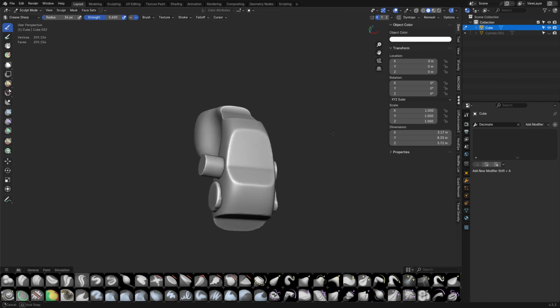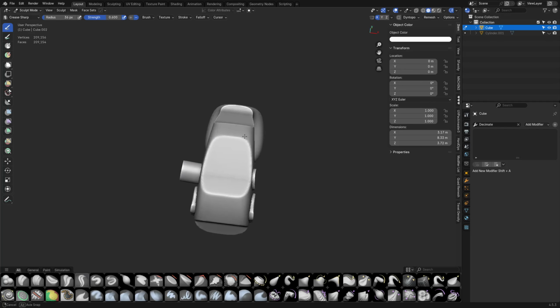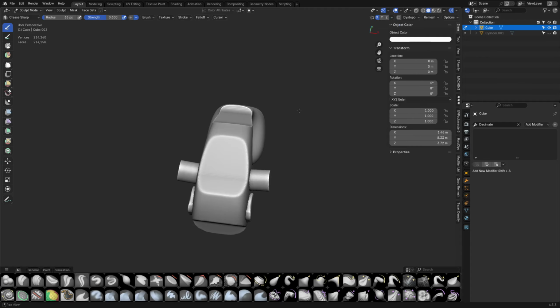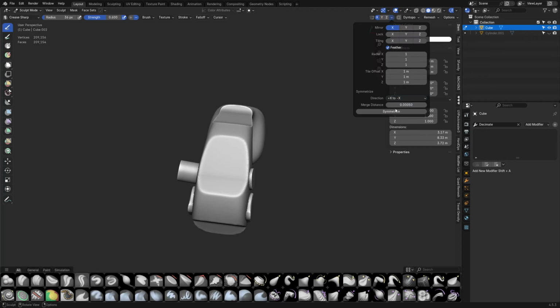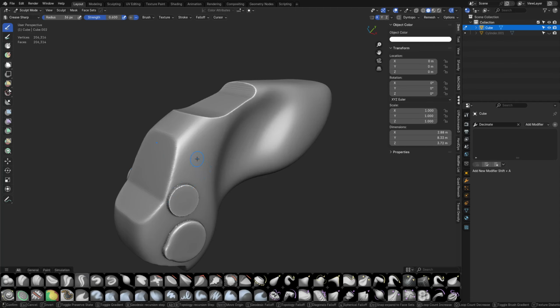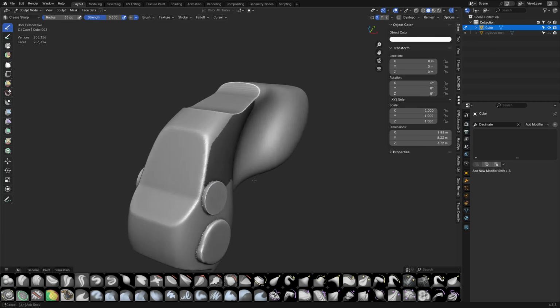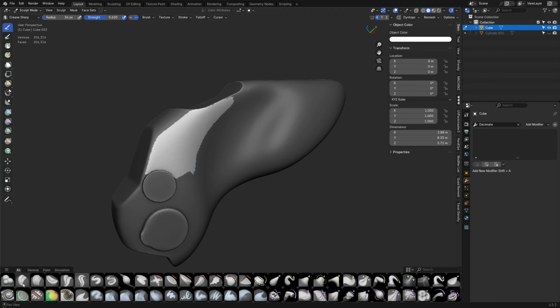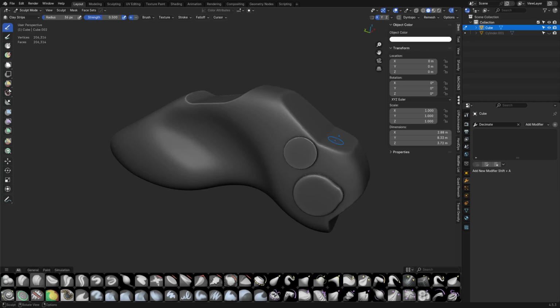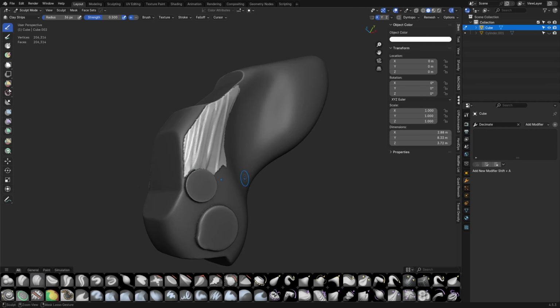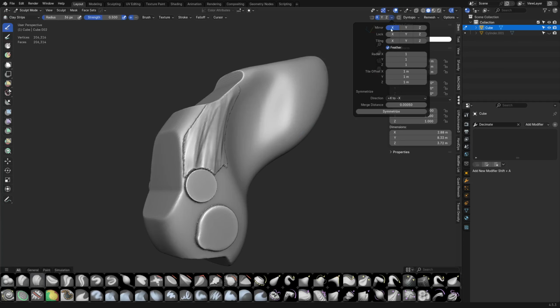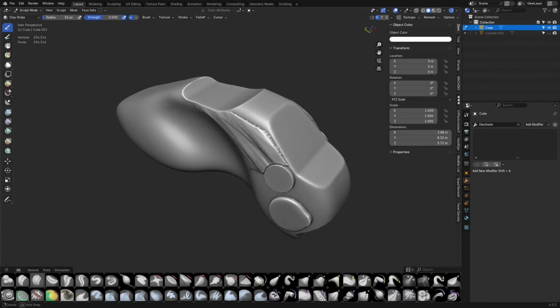And truthfully, when we're working on something like this, you can see, for whatever reason, we did that. Don't forget to symmetrize sometimes. Blender will lose symmetry with certain tools. In our case, maybe we go the other way with that. Let's do positive X and negative X. So like Alt-Shift-A, for example, is a quick way of masking by surface. But unfortunately, it doesn't really know that you're trying to do symmetry there. And if we do this and we sculpt here, it doesn't know that. Okay, so you can do this if your object's symmetrical, and as long as it's a voxel system, you should be okay to just clear that and re-symmetrize the way you see fit, right?